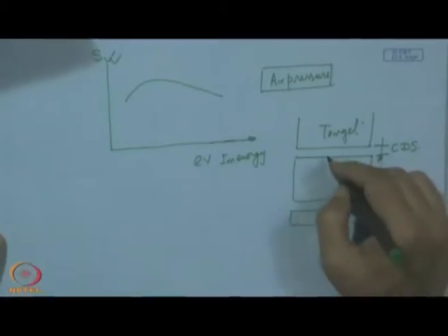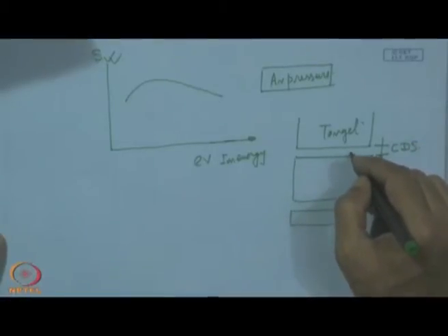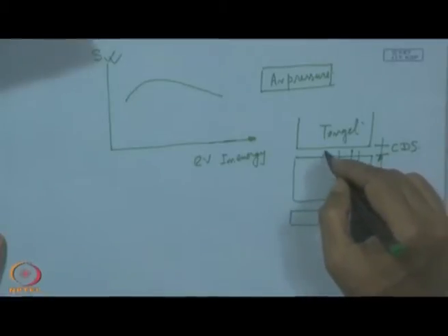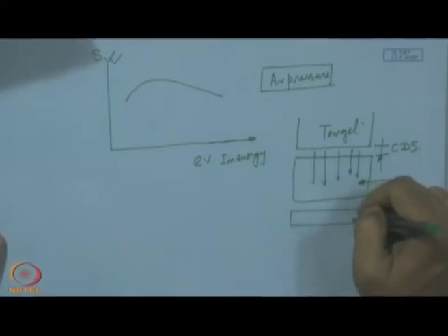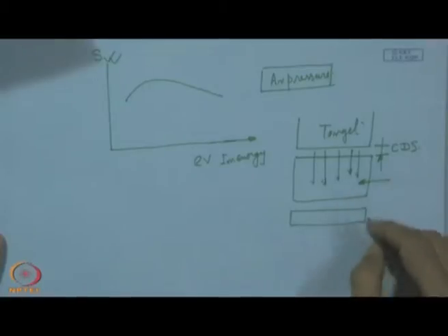Now, what happens is these secondary electrons have free access and they can move in this direction, and they can impinge on the surface of this substrate, and in this process it is high energy impingement, thereby increasing the temperature of this substrate, and it could be that the quality of the coating can also be a little bit affected.